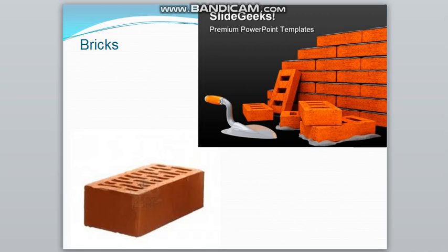Another test performed on bricks is the dimension test. According to Indian Standard 1077, this test is performed. 20 pieces out of selected pieces are taken and laid flat. The tolerances and the sizes of bricks are fixed by giving minimum and maximum dimensions. It follows this method of measurement. The batches are likely to contain bricks outside the prescribed limit of tolerance.